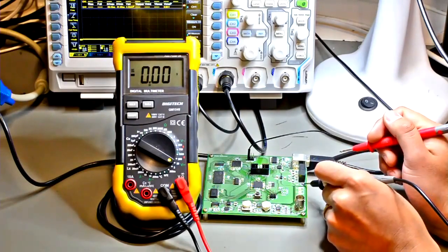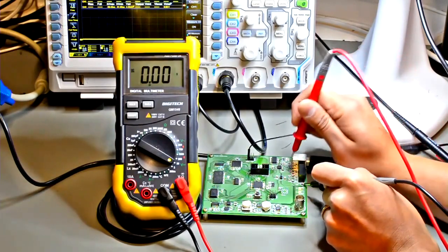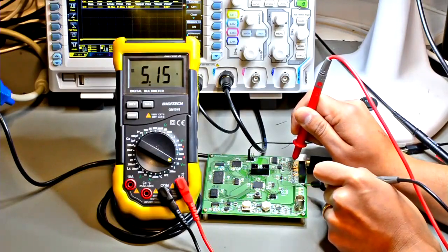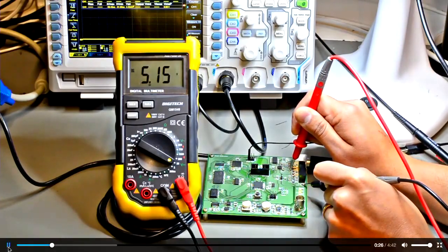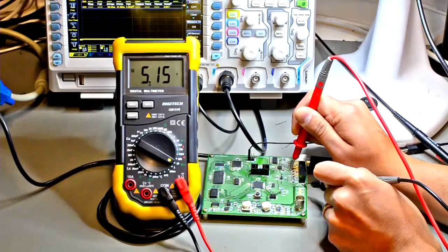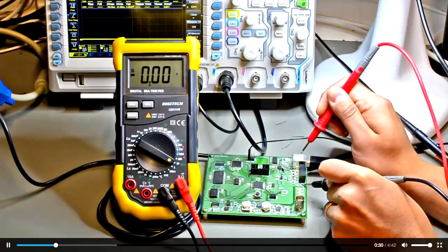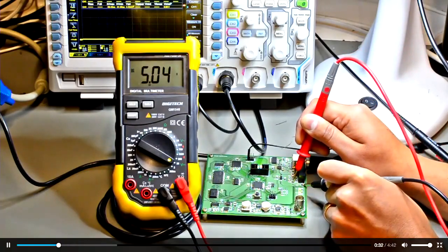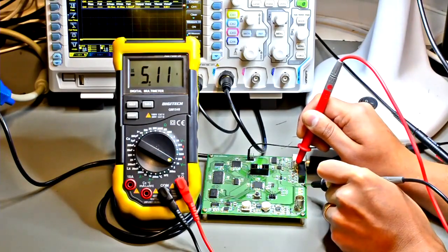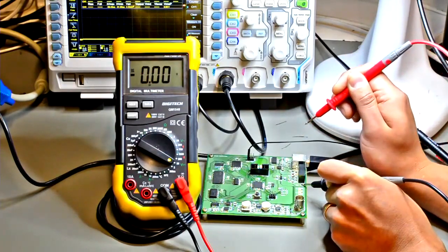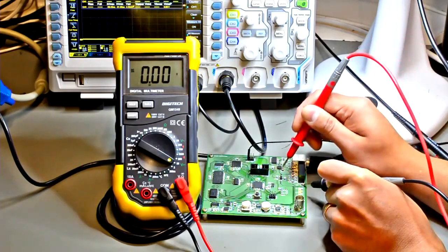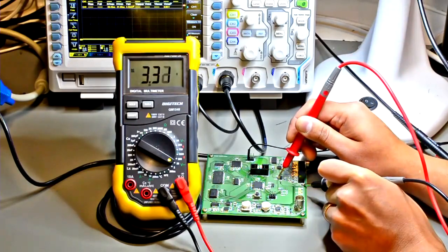The first thing you're going to want to check is the USB power supply rail. You should get around 5 volts on this rail. Please check in this order so that you are systematically debugging your DSO. The next thing to check are the +5 and -5 outputs. You will have large test points on your boards that show this. Next, check the 3.3 volt signal. This comes from the DC regulator and you have a small test point on your board to check this.